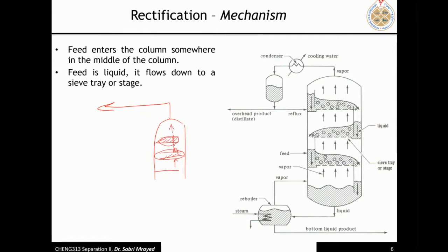So the composition of the more volatile component, Y, in, say, stage 3 and stage 2 is all the same, there's no change. Why? Because there's no mass transfer. Why is there no mass transfer? Because there's no other phase. We have to keep two phases throughout the column. And we can do that only by taking part of the top product, condensing it, and returning it back, so we can ensure we have liquid at each stage.